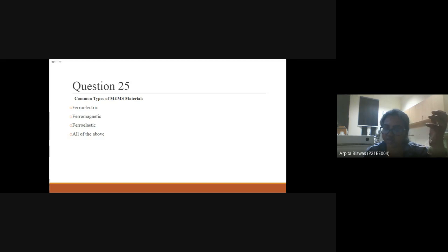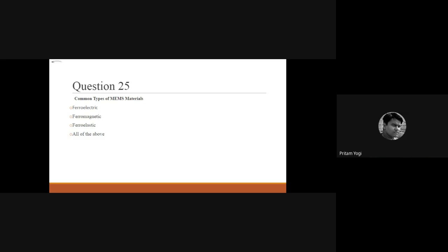For removing the silicon dioxide, at first we dip into the BHF solution. For the front side, polysilicon is present for the IDE pattern. There is some material present for the IDE pattern, so we have to save that also, using any method.